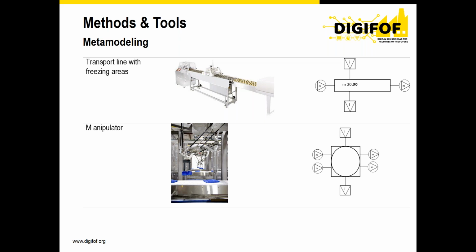Another element that is many times present in the food industry, and in confectionery especially, is the transport elements. We abstracted here; the line is not very crisp, but we decided that transport lines, or transport machines, are the machines that do not change the material. So the same material that enters also goes out. Normally, what we look at in this case is that the mass, the packaging and the geometrical details, so to say, are preserved. If I have a number of units on one side, I should have the same number of units, similar, with no important changes, on the other side.